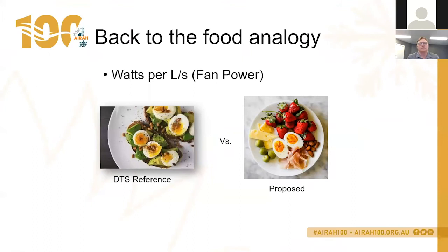So that, in the system-based approach, looks at the watts per litre per second of the fan power for the minimum compliant fan from a deemed to satisfy perspective using the component-based approach, and then compares it to your proposed system watts per litre per second.